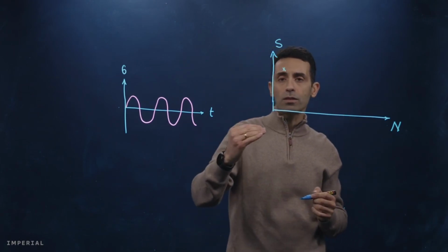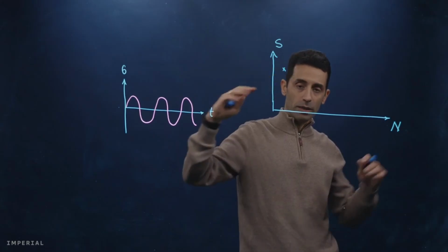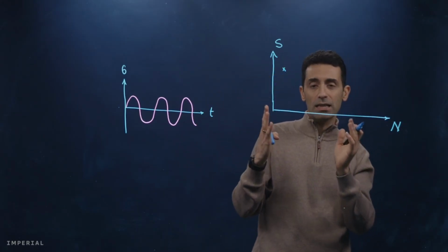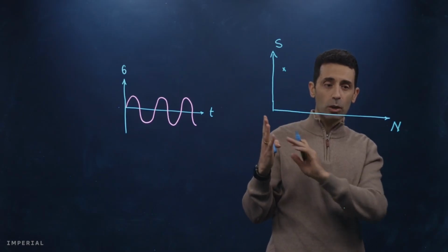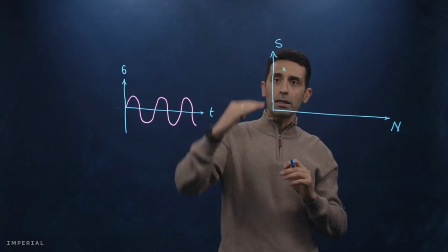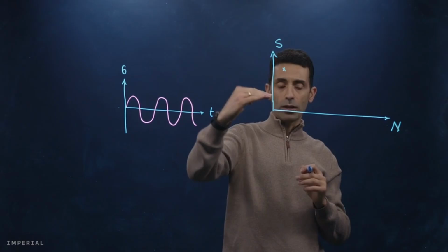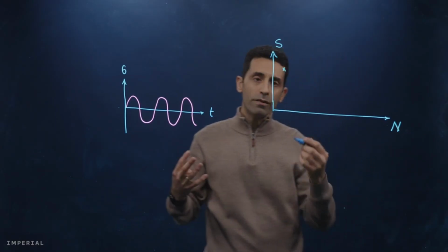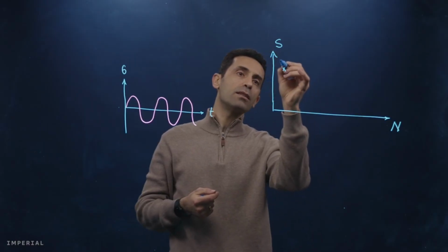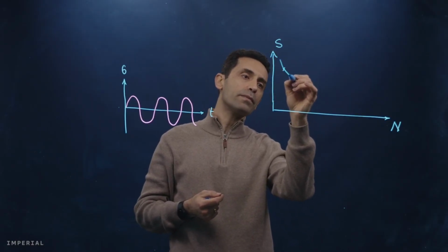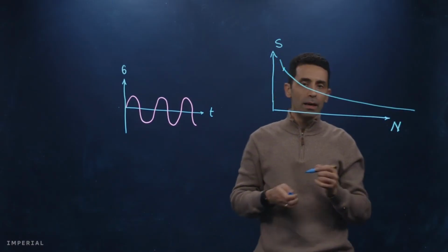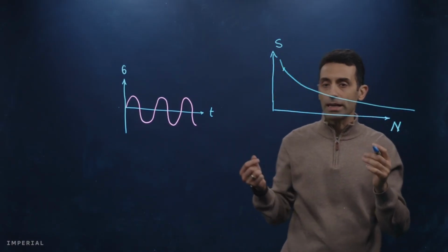So of course, when the magnitude of the load that we are applying is larger, the structure can sustain fewer loading cycles. But if that magnitude is lower, then it can sustain more cycles. So if you do that, then you will see that we will have a curve that could look like this. Okay, so we call this curve an SN curve.